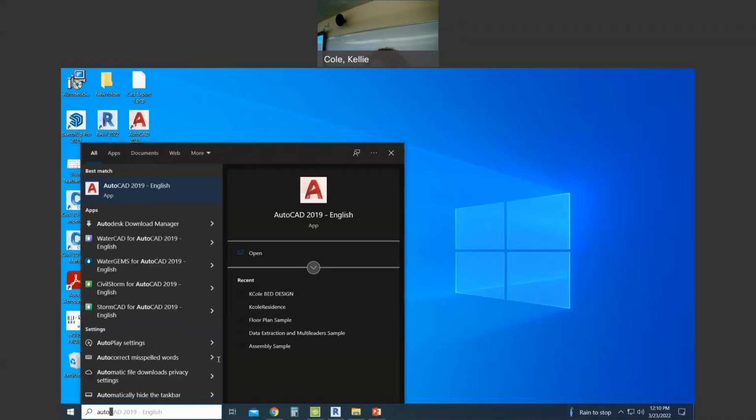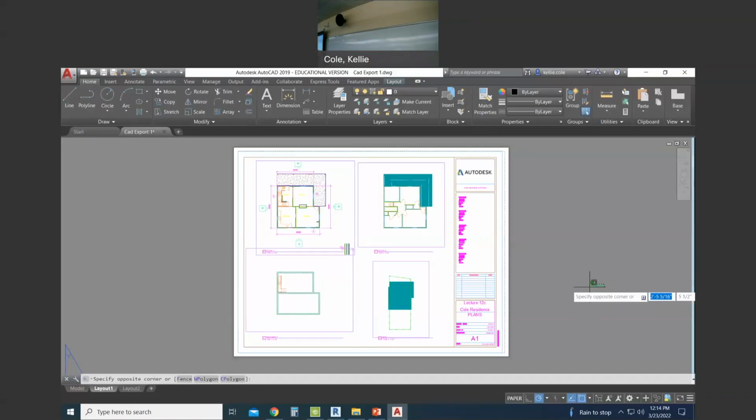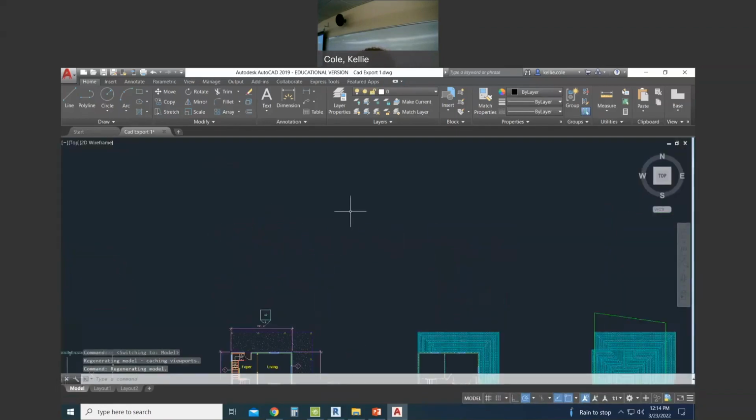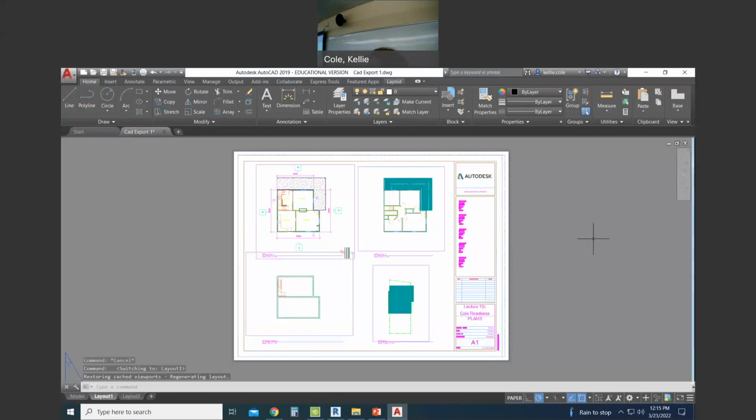We're going to open AutoCAD. Has everyone found AutoCAD? Yes. Great. I want you to open up your file in there. AutoCAD has two worlds similar to Revit, where we are drawing in that 3D model world of Revit. That world is the model tab at the bottom of AutoCAD. So when I tap the model, I see all of my drawings. So that's where we're drawing in 2D. But then we flip to the tab of Layout 1 as our sheet file. So the drawing doesn't exist on the layout. I've got to double click in that view, and then I can start working in the drawing. So it's very much like when we pull drawings onto a sheet.